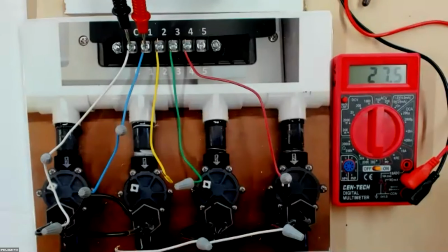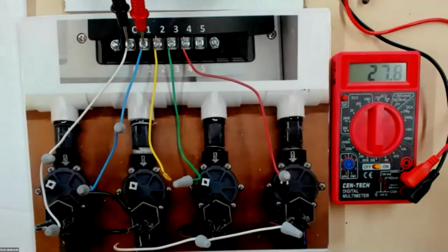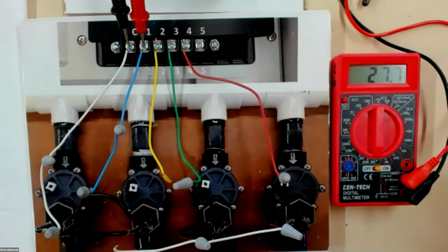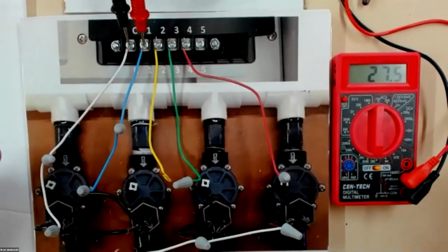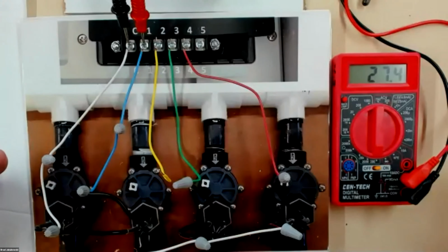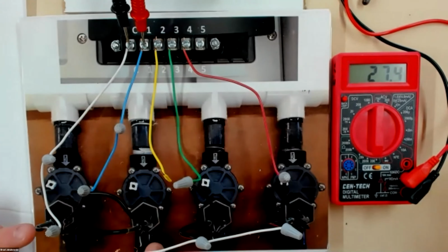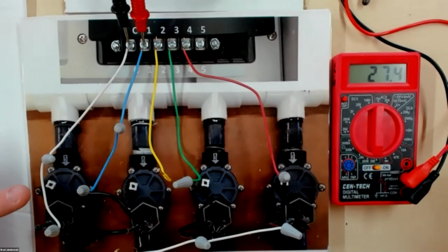13.3. Thank you. That is the correct number. I didn't change my common wires because it didn't matter. Okay, good. So that actually should work. So I got that one going through there and that one going through there. What's going on with mine? Trying to think. But anyway, you should have 13 ohms there. So when you hook 2 stations together in parallel, it will cut your ohms, or your resistance, in half.